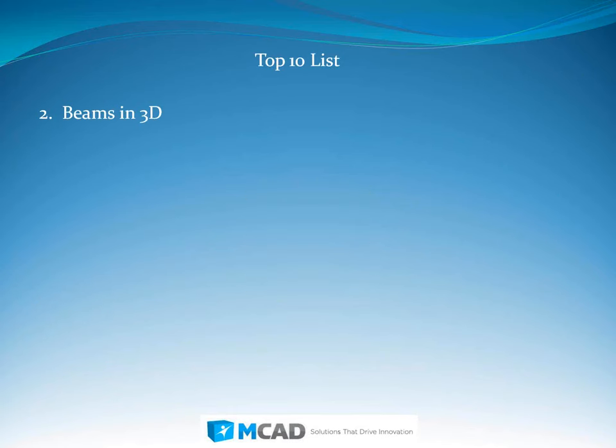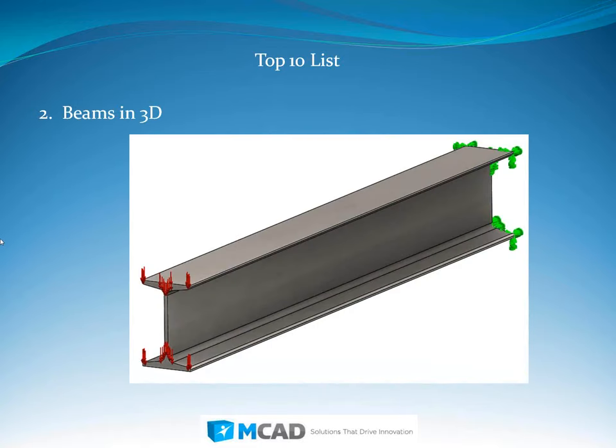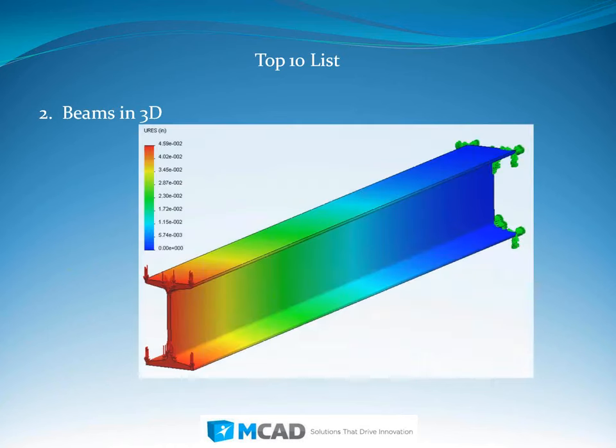All right, for number 2, as we had for the shell elements being able to be mapped over to 3D, we can do so as well. We've been able to do this for a little while with beams. So looking first at a solid representation of this structural member and set up as a cantilever beam, if we look at a deflection plot of that, this is what we see in terms of solid mesh elements.